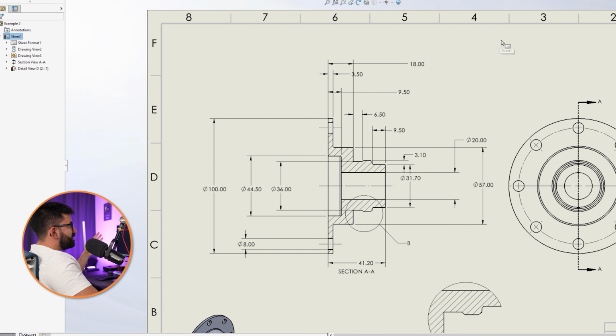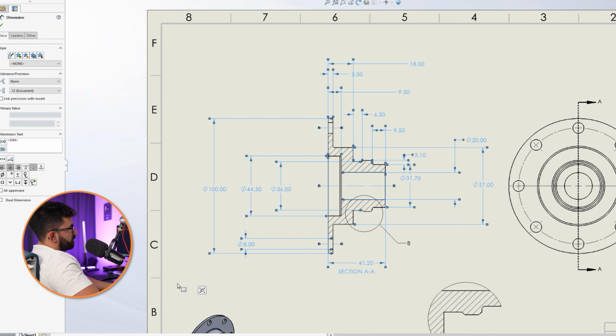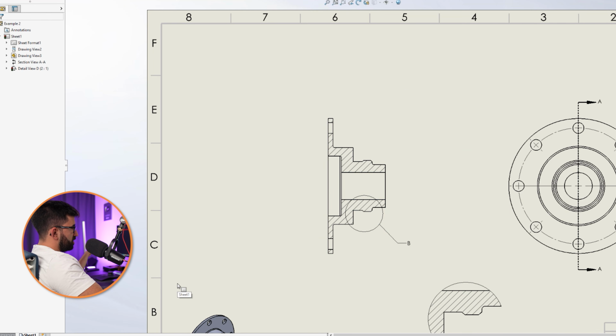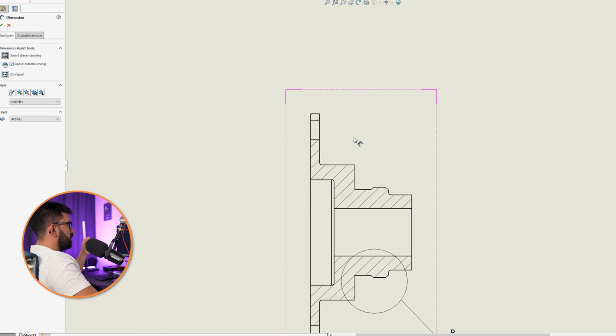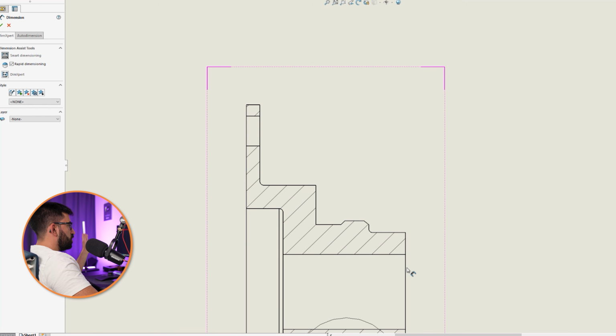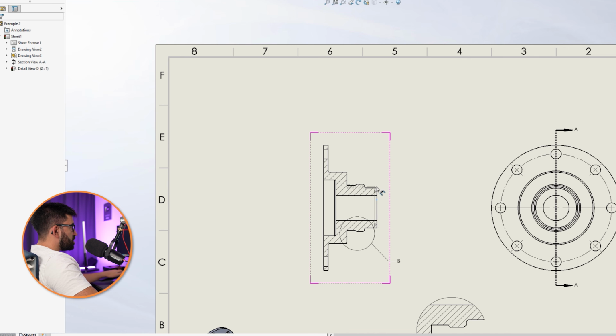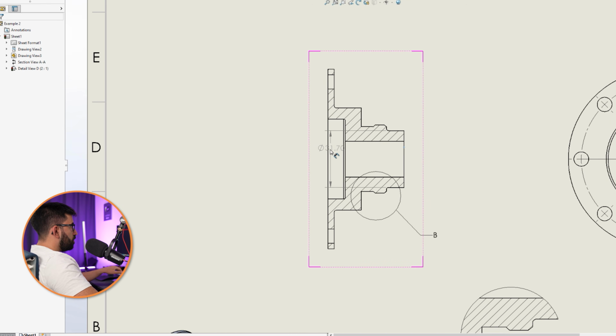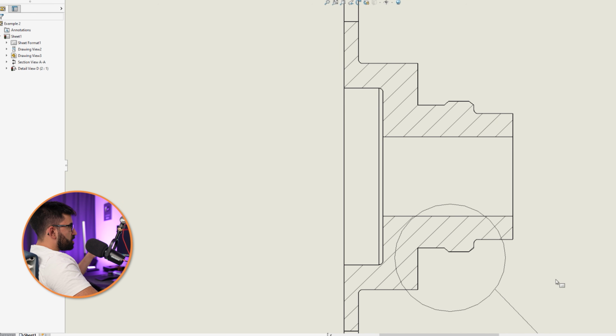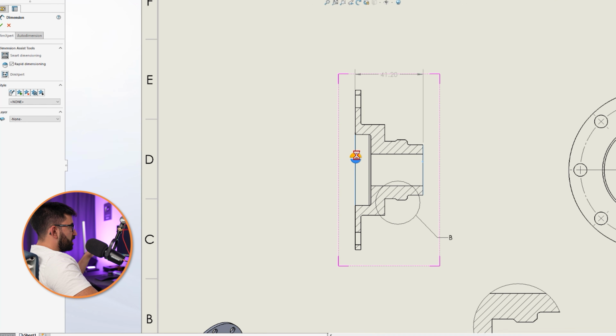Now, I want to delete these auto dimensions by selecting everything. They're on the top level, so if I press delete, I only get rid of the top level. If I do this again, I get rid of the part, which I don't want to. Now, I want to assign some dimensions, like one or two, and tell you what else we can do here. From this line to this line, you see that? This half circle just gives me the auto position of the dimension on the top or bottom. If I just move my mouse, zoom in, zoom out, that auto dimensioning goes away, so I can press escape to bring it back. Okay, press escape and do it again. Like that, top or bottom.